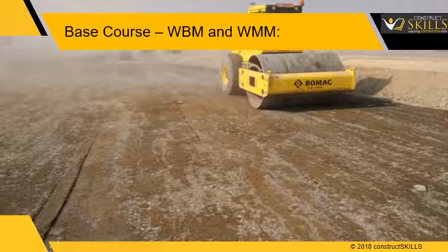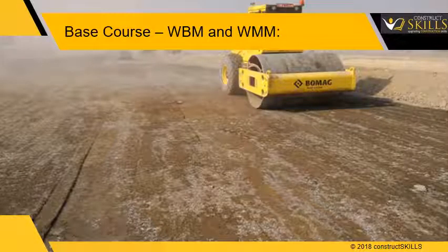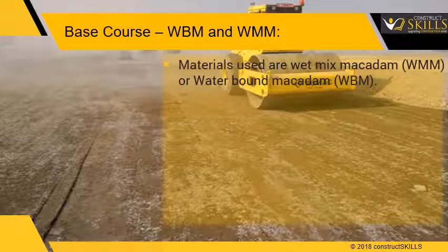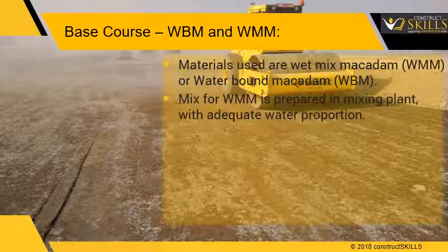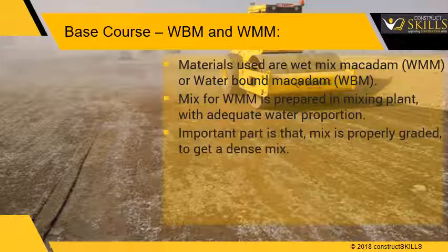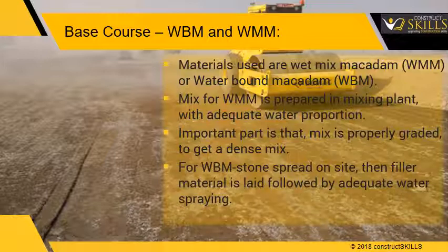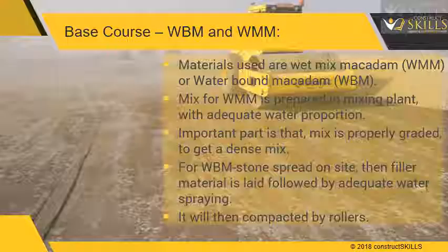Base course, WBM and WMM. The materials used in the base course are wet mix macadam and water-bound macadam. The selected mix for WMM is prepared in a suitable mixing plant, with an adequate proportion of water. The important part is that the mix is properly graded, to get a dense mix. For WBM, the stones are spread on site, then the filler material is laid followed by adequate water spraying. It will then be compacted by rollers.